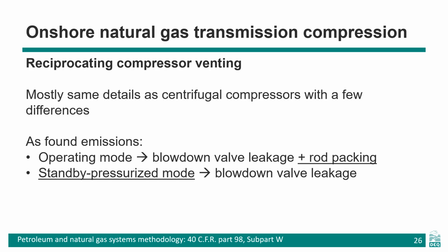Reciprocating compressor measurements are similar, but there are a few differences in measurements that can be taken and where they are taken. Reciprocating compressors won't have wet seals to monitor. However, rod packing must be measured for leaks when a reciprocating compressor is measured in operating mode. For reciprocating compressors, as-found measurements may also take place in a standby pressurized mode and should be measured for leakage at the blowdown valve in that case.